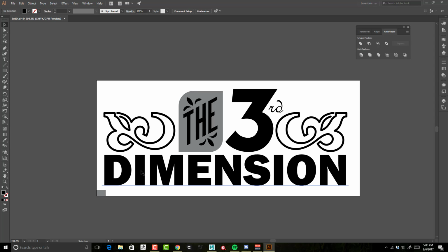So we've already created the dimension word at the bottom. Now I want to bring in these other guys into Maya. Now you'll notice that I have a little box down here. This is to keep everything in line. I want to bring these in as different nodes, as different files, so I can manipulate them differently. With this guy created and selected, whenever I import these, this will keep the registration right.